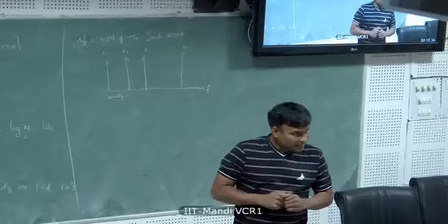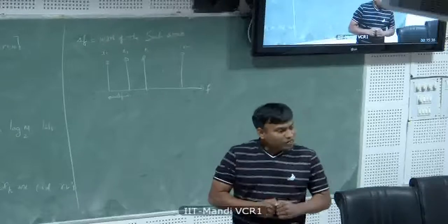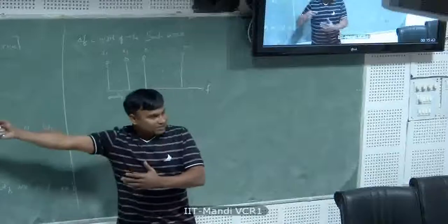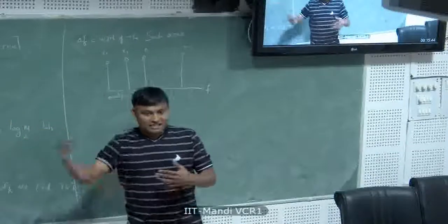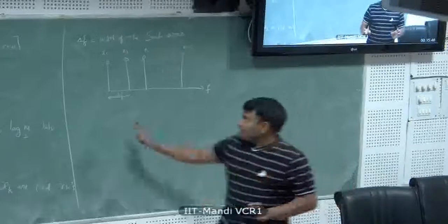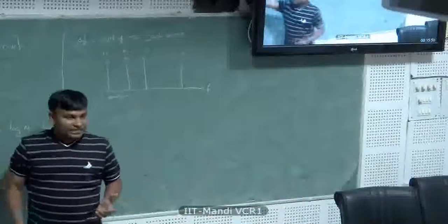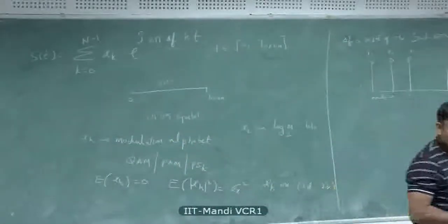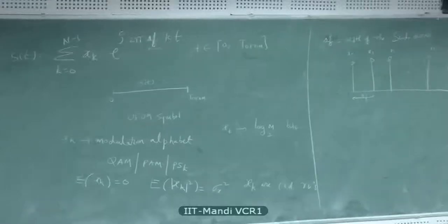Let us say your bandwidth is 20 megahertz. You don't fully occupy 20 megahertz. If you do, then there will be side lobes. That means you are exceeding the 20 megahertz assigned to you. So you reserve some 2 megahertz, and at the edges you null out some carriers. What do you mean by nulling out? Well, make some of the xk 0 at the edges. Okay? You make some of the xk 0.